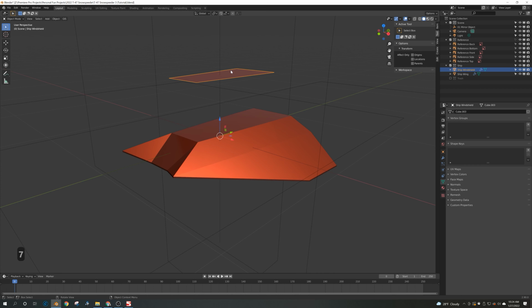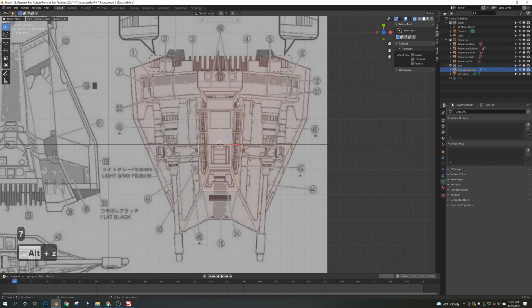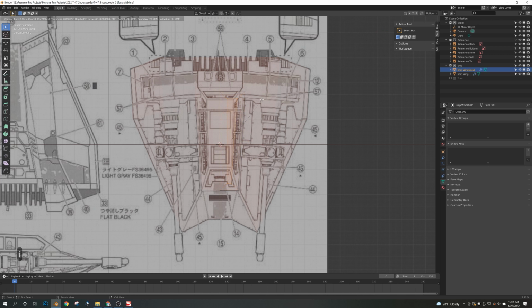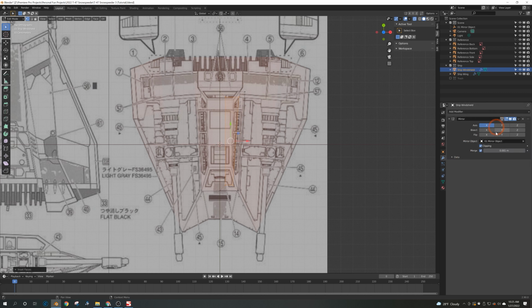But let's go orthographic view. 1 to see your vertices, A to select all, and I to inset. Is that what we want to do? That is what we want to do. Yeah, that's what we want to do. So we've inset it. Now we've got the vertices that we need for the top. We've got them connected by some edges, and this is still mirrored with clipping.